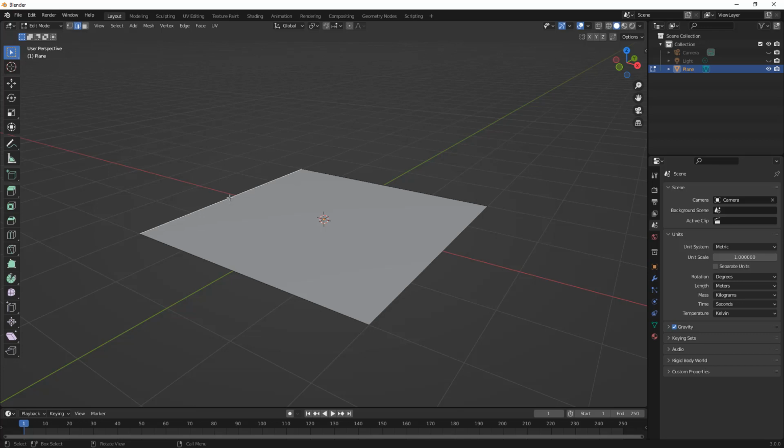And when we select a single edge and we hold down the Control or Command key, it's going to do the same thing that it did with vertices. You can see again that we've got the dialog where we have our pick shortest path. This time you can see that we've got some options for tagging edges. We're not going to worry about that right now. Mainly we want to focus on the workflow to making these edge selections.